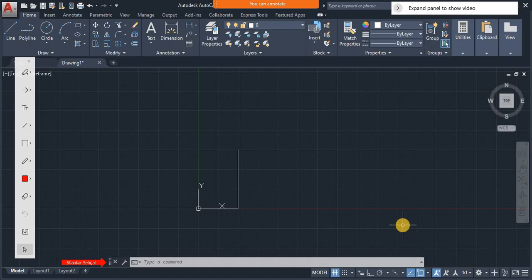These two lines have been drawn using the absolute coordinate method. Now instead of using the coordinates, I can also use ortho mode here. So I click on ortho. Now you can see I can draw only vertical and horizontal lines. For example, if I give the line command, and the first starting point, instead of specifying the coordinates, I am clicking on this endpoint, and you know the exact endpoint will be picked up. Why? Because the OSnap is getting highlighted.